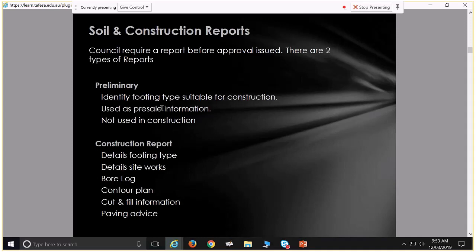and typically we know that we're dealing with reactive soils in South Australia. As a percentage of, let's say, the cost of your footings, if it's medium to high, it will be about 12 to 15,000. And then it's around the 20 to 25,000 if it's going to be reactive for the same sort of footing system. Percentage-wise, yes, you might save yourself a bit of cost, but typically for a residential application, you're not getting a preliminary report done.